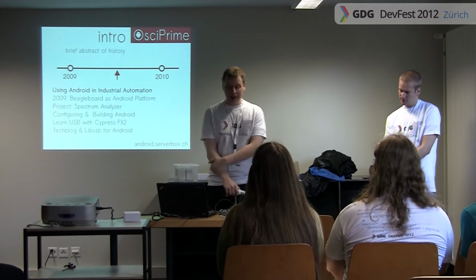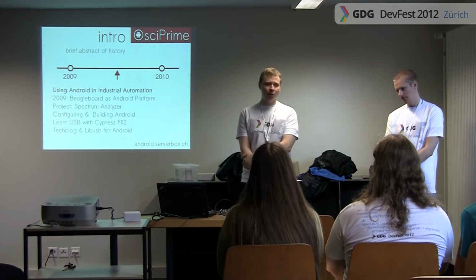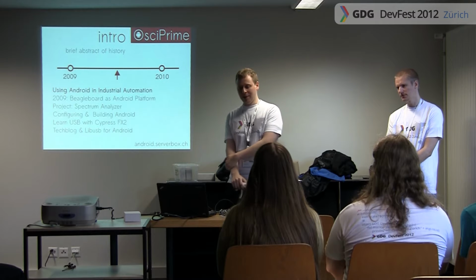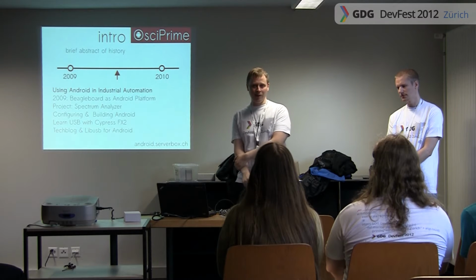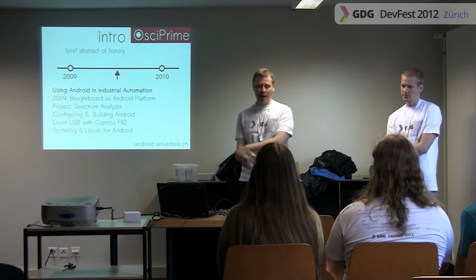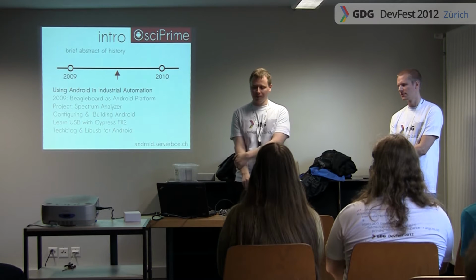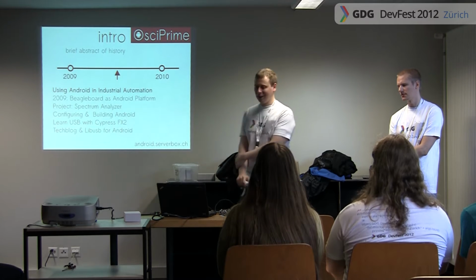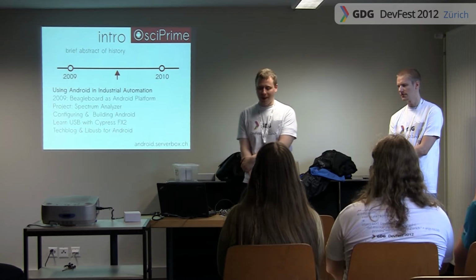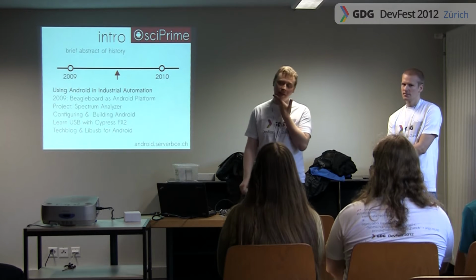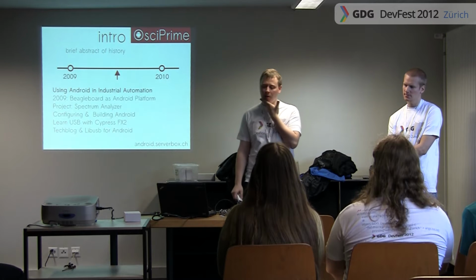And what we learned there in the project was how to build Android, how to configure, how to compile the kernel, how to get everything together and boot it with U-boot, and so on. And also how to use NFS file system, and all the technical stuff you would require to develop on embedded systems. And it was the initiation of our blog,